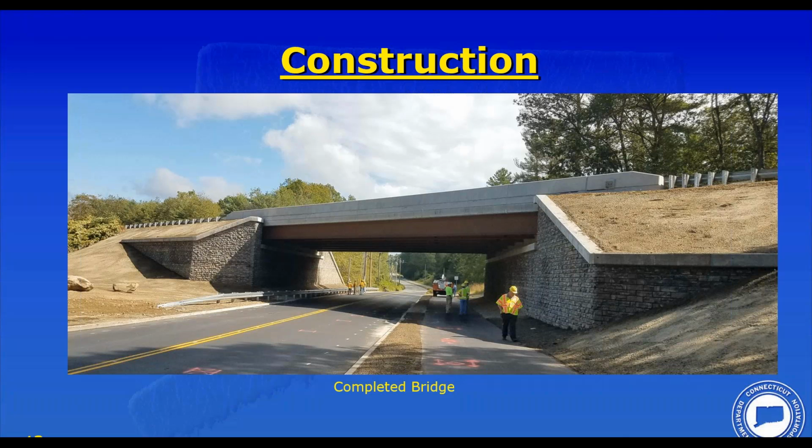Connecticut does build quite a few steel bridges. We actually aim to get about 50% steel, 50% precast or pre-stressed concrete. This particular bridge made sense to go to steel. So it's a weathering steel bridge. With GRS-IBS, we have no approach slabs, we have no bearings, we have no joints in the bridge. It's a simple saw and seal joint at the top. No approach slabs, which definitely reduces cost. So these are very cost-effective structures.